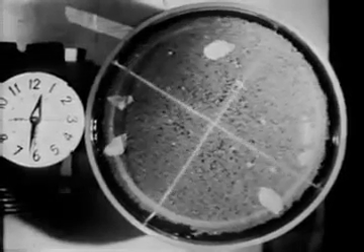When a fluid flows around a sharp edge, viscous forces in the boundary layer produce a separated flow. The fluid which has been affected by concentrated viscous forces forms a concentrated vortex.